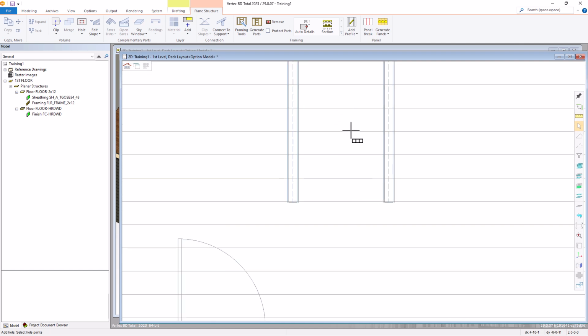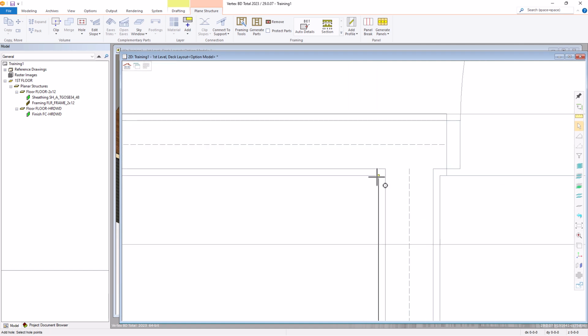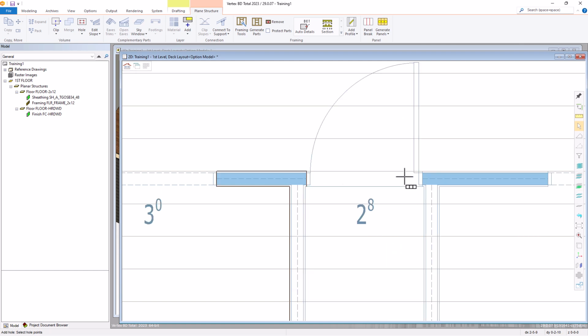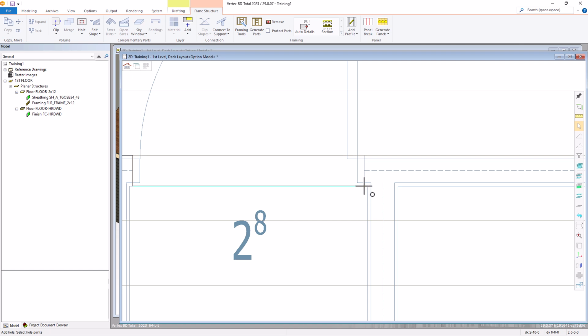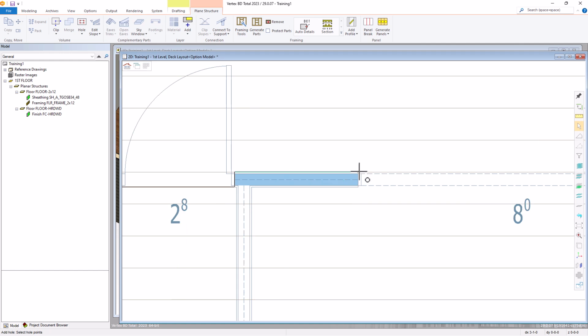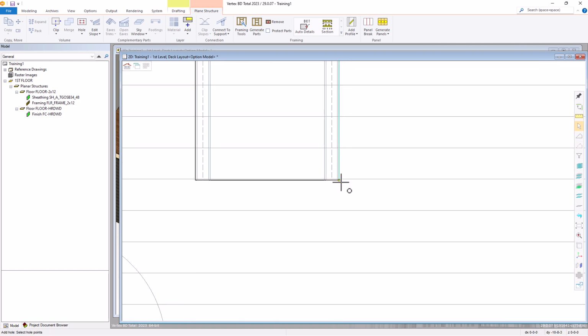Since this is where we want to omit this and also underneath the wall, we're going to start at this corner here, go all the way across, up to our drywall, to that drywall corner, to this corner. We're going to come back down. Let's go to the edge of that line. So we do want to see the hardwood underneath the door there. Back up and just to this side of the opening, straight down to the other side of the drywall, and back to our starting point.